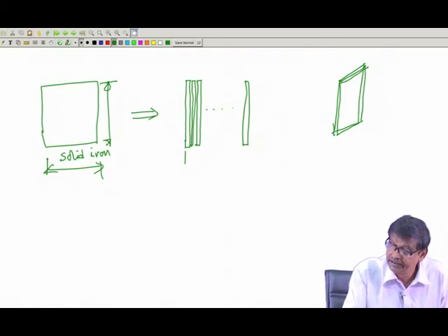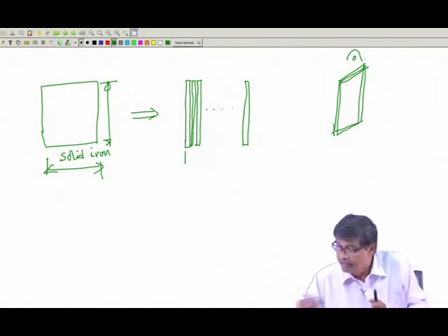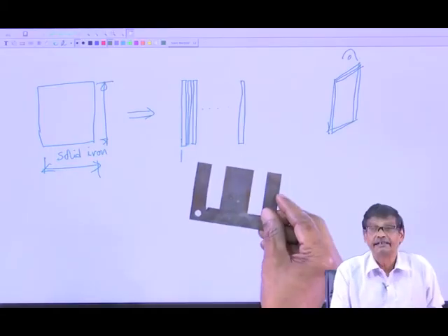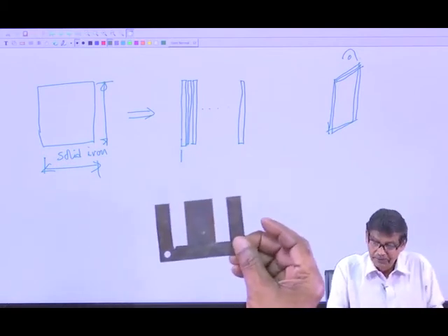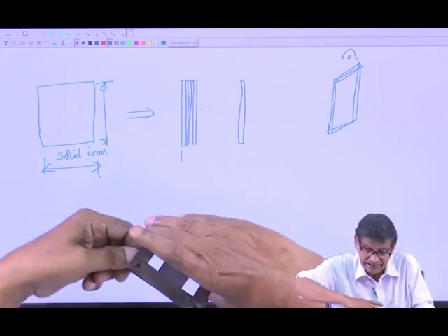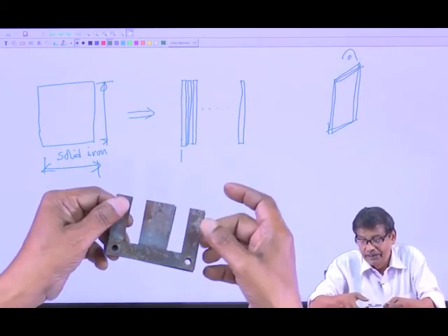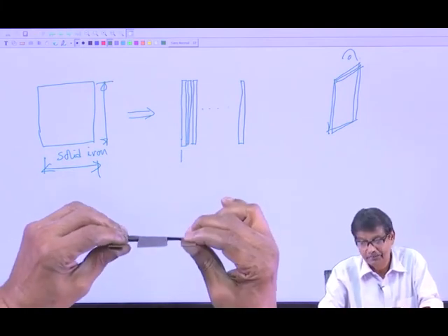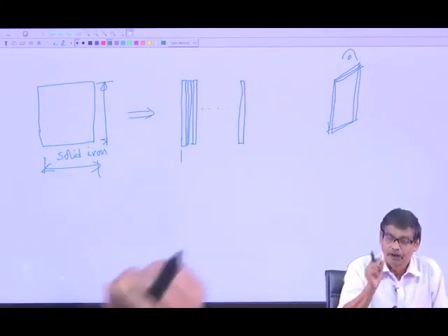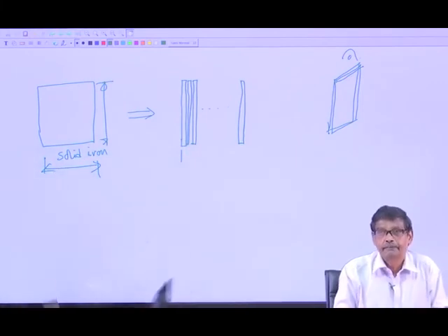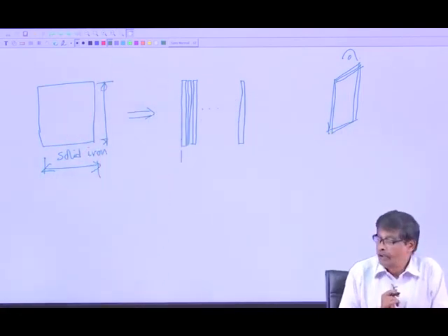So, the sectional area from the top, if you look, it will look like this, okay, thin plates. I will show you. Suppose these are thinner plates like this, a magnetic circuit, you are able to see now, thinner plates. You take iron plates and you put another like this. I have brought only two, you can put several such plates to have a height here, that is the width of this magnetic circuit, this portion. So, many thinner plates of small thickness you use and stack them together instead of using a solid iron.